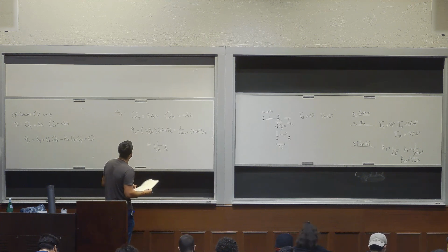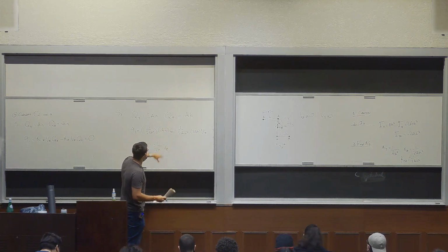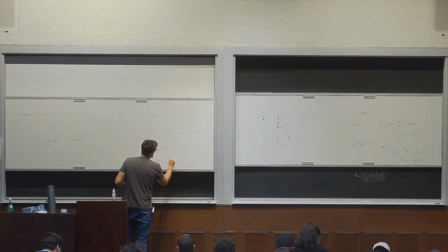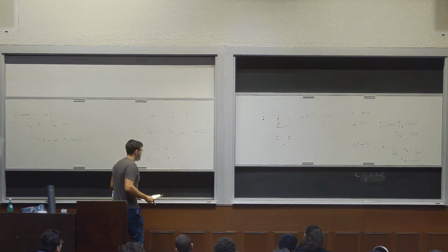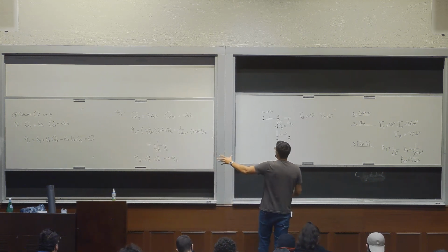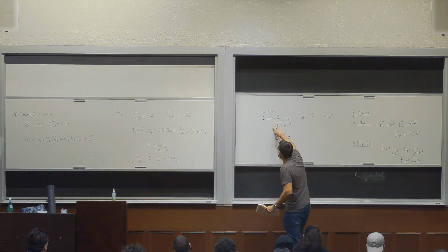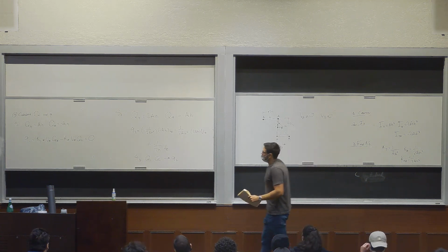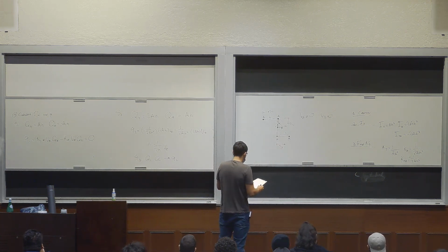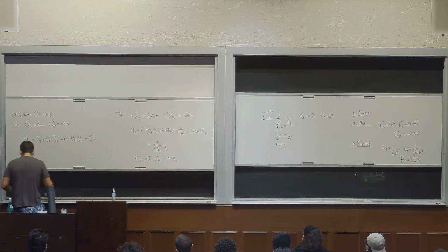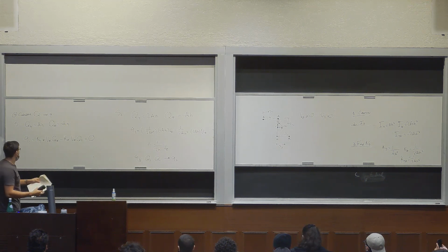And there's nothing for Q3, but you could do the same thing. All the areas before the relevant things, find the Q's, QY, QZ. You find Q3. And again, to find the shear stress, take those Q's. In these cases, they're constant values. So you'll have one value here, one value here, one value here. You can divide those by the thickness and find the shear stress. So simple, easy peasy. And now what I think is the most important part of this discussion, and the last part, which is good,